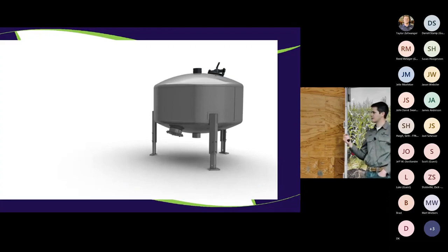And part of our startup process is checking to make sure that when the filters flush, they aren't flushing the sand out with it. There's a valve we start closing down to limit how much water comes out so it doesn't carry that sand out with it.